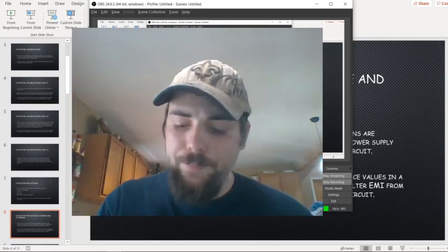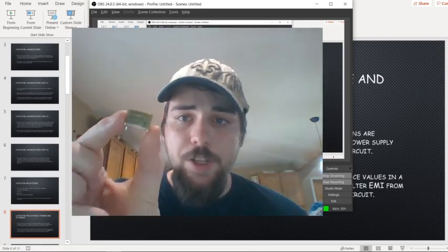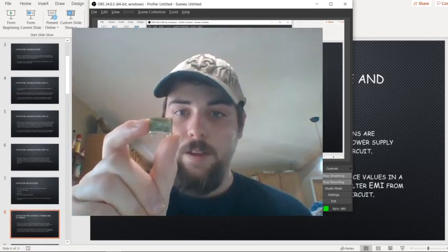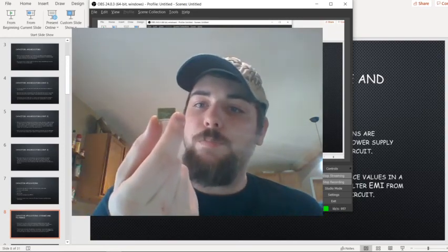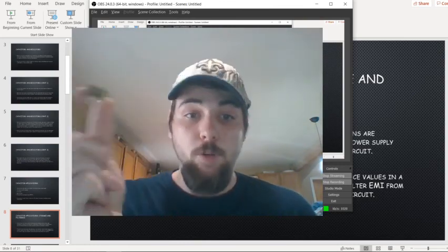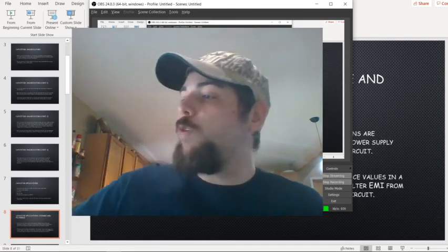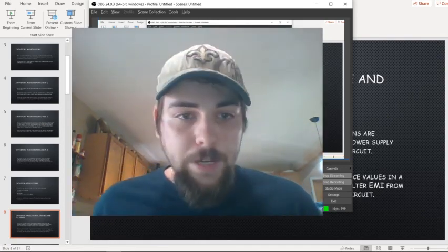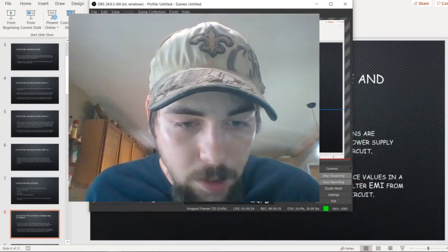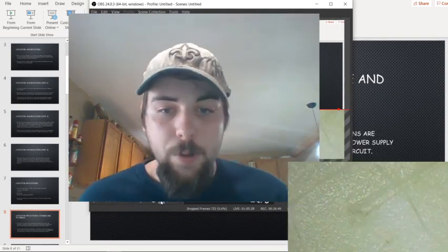It's kind of hard to see, but now I wanted to take a little bit of a second to talk about these guys. Now, these guys are the same things as the other ones, but these are horrible. And it's not because of their specific dielectric or their performance as a component. It's the actual construction. And I'm going to switch over to the microscope here, and we're going to look at that one under the microscope because this is a very important thing to look at. And this goes right to the heart of what I'm trying to say. You need to be careful about which components you're selecting.